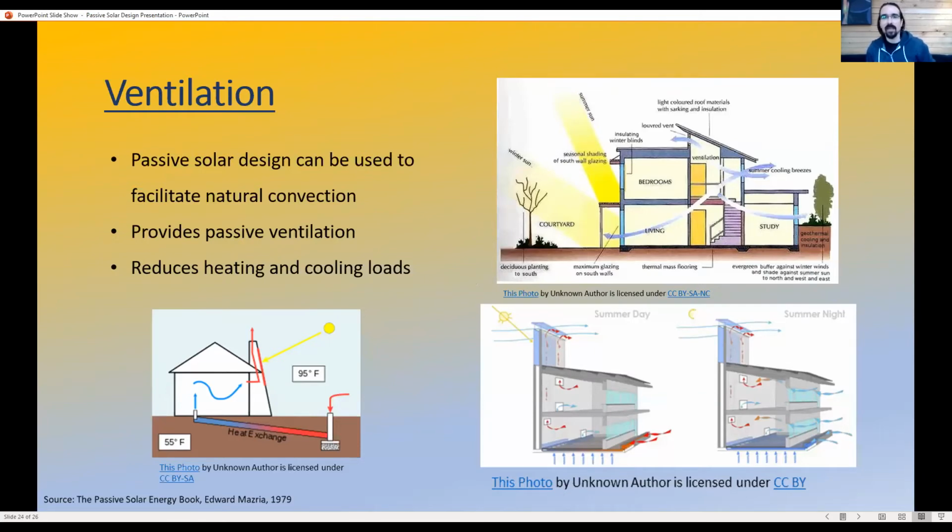But ventilation is designed. You can design a house to use passive ventilation, where the heat transfer, the radiant energy in the house actually encourages ventilation. Open floor plans encourage ventilation, and natural stack effect and convection properties can encourage the natural ventilation, so that you don't need a mechanical fan or anything to actually move the air through the house.